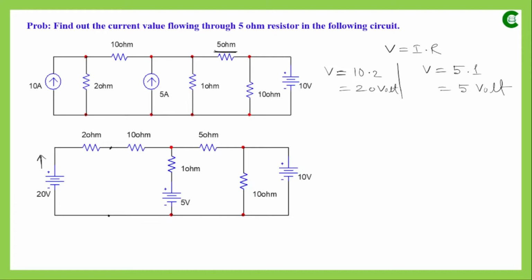Then we had this resistance value, and with that in parallel this voltage source. So it has been kept as it was in the original circuit, and this time the voltage source is connected in parallel with this resistance value. So it's not a current source, it's a voltage source. Since we want to apply KVL or mesh analysis, we want voltage sources to be in the circuit. So finally the modified circuit will look like this.